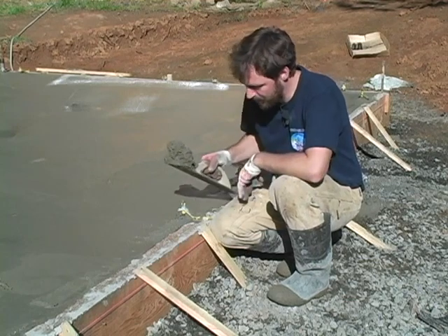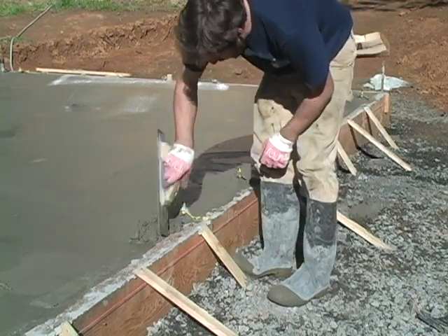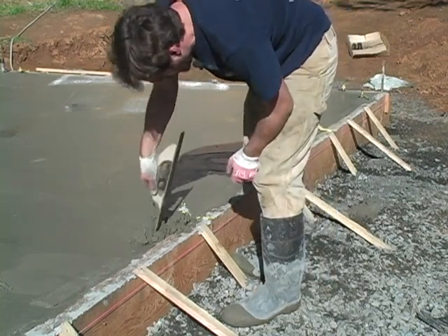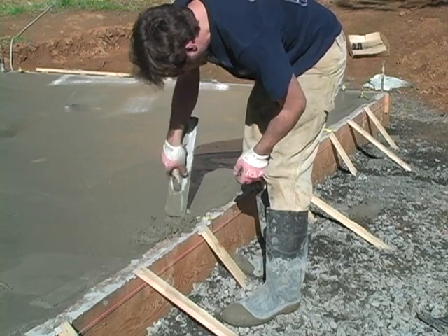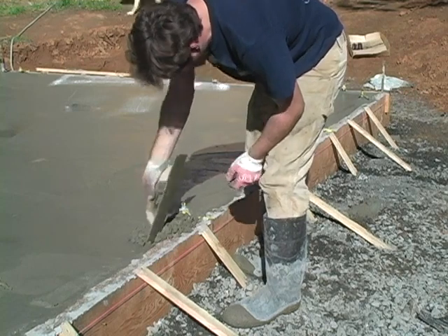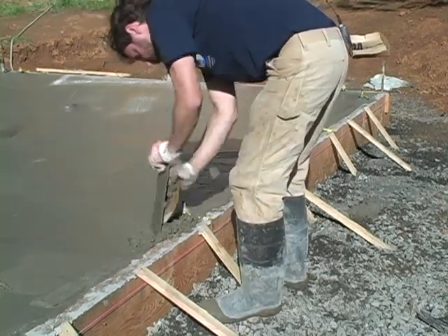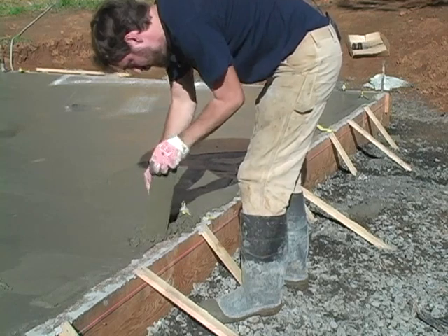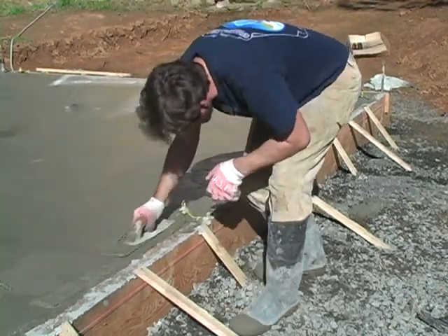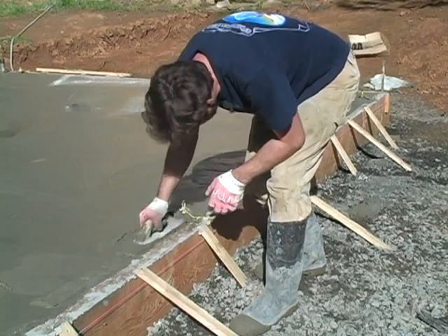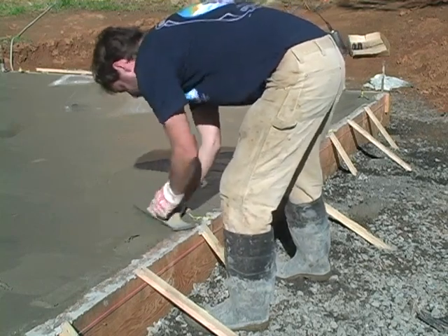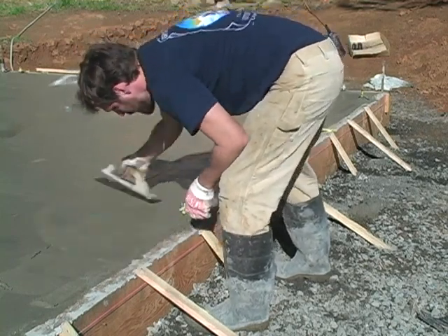Now right here we've got a small hole in our concrete, and we're already pretty set up. So again, I'm going back to my pile of clean concrete that I left over. I'm going to tamp this in here, just sort of connect it, mix it up with the concrete underneath it. I don't want it to just be a surface patch, because then it won't adhere and bond well. So now that I got it in there, I can really jam it up, put some pressure on it. And just with this float, I can actually bring a lot of cream to the top. I don't have to retamp this whole thing out. This is just a good way to fill in low spots.